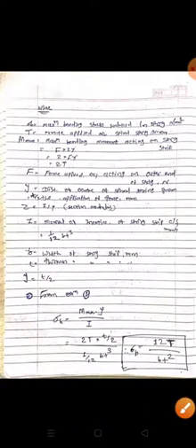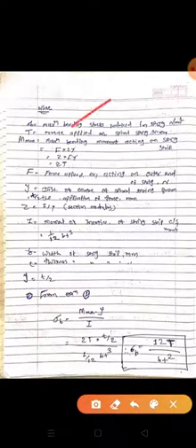Next, what is sigma B? Sigma B is the maximum bending stress. T is the torque applied on the spring. M max is the maximum bending moment, which we already found. F is the applied force. y is the distance from the center of the spiral spring to the application of the force, and it is equal to t by 2. Z is the section modulus, Z is equal to I by y.